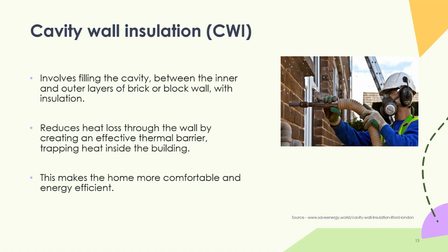So when you're trying to replace the failed insulation in that situation, actually what you need to be thinking about is having the material removed, letting the wall dry out completely, then fixing whatever holes or other entry points the water has before you refill it. Otherwise, you're just going to create the same problems again.